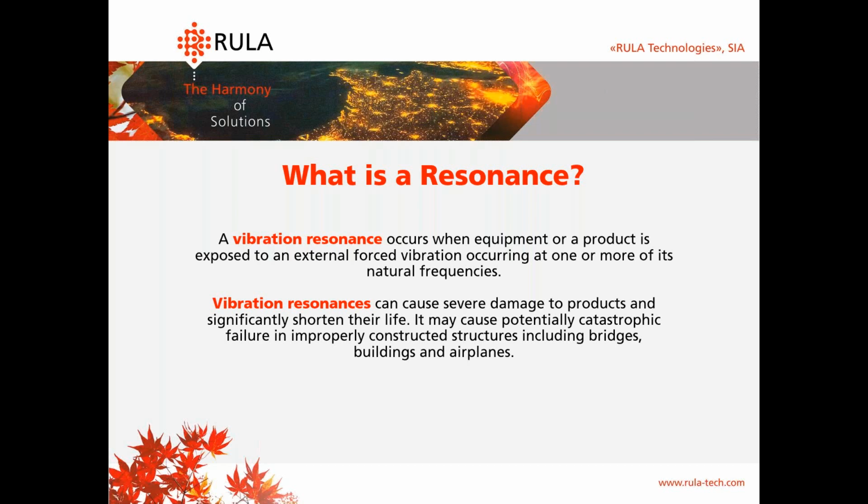So, what is a resonance? A vibration resonance occurs when equipment or a product is exposed to an external forced vibration occurring at one or more of its natural frequencies. Vibration resonances can cause catastrophic damage in poorly constructed objects such as bridges, airplanes, or buildings.